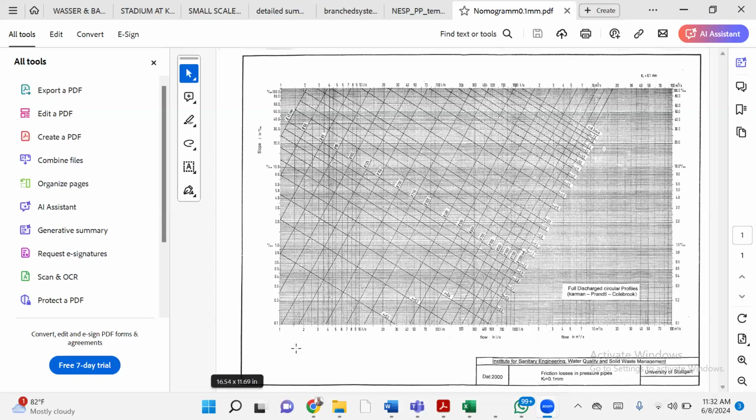The rule says that anything less than 1 liter per second, you assume the value for 1 liter per second. Let me say it again. Those of us who are civil engineers know you cannot design a column with less than 16 mm. You cannot space your reinforcements more than 300 mm. That's what we call limiting values. In every design, there are always limiting values. Even if the thing will not carry anything, this is the minimum you can use. So in this case, even if the flow is 0.8, you just assume the 1. Even if the flow is 0.2, you use the value for 1. And that is what this chart is saying. So 1 is the limit.